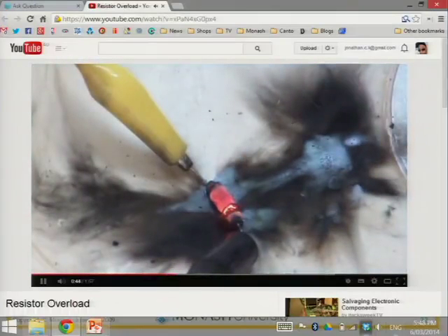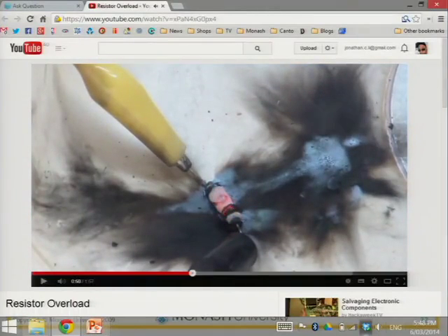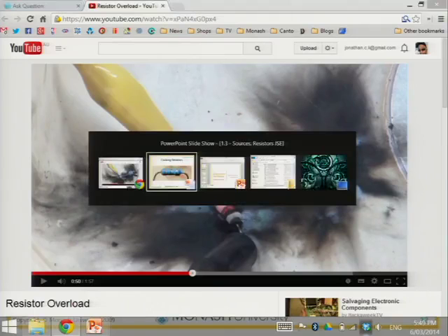This can basically happen if you get a short circuit. You know how we always say short circuits are bad? If you get a short circuit in one of your circuits which takes current from the mains, you might be getting tens of amps through your electrical hardware. If your hardware has resistors in it and they're passing lots and lots of current, then this can happen. And if this happens more seriously, you can start fires, which does happen with poorly designed electrical circuits. So cool, but also dangerous.